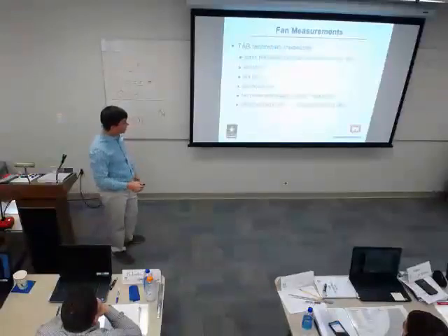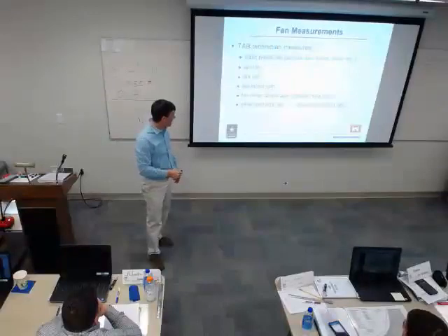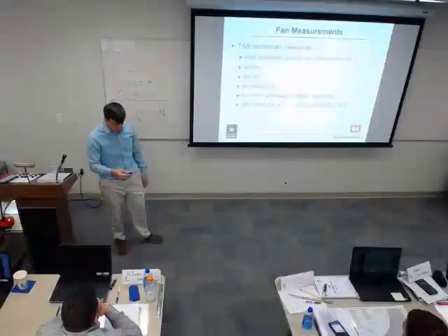We're also going to check the electrical characteristics of the motor: amperage, voltage, frequency. And there's a few other random things at the bottom of that report, like belt sizes and sheave sizes, that also go at the bottom of the report.